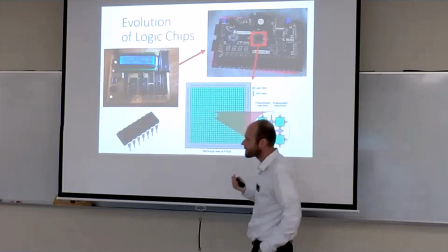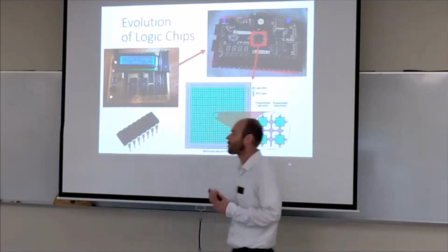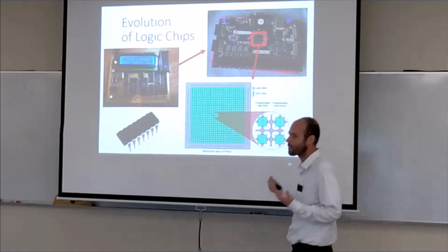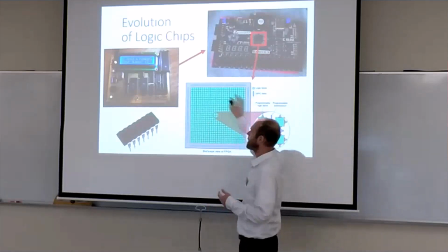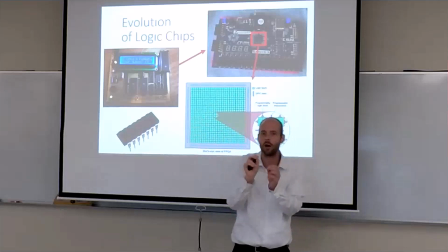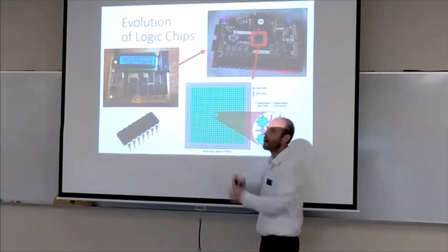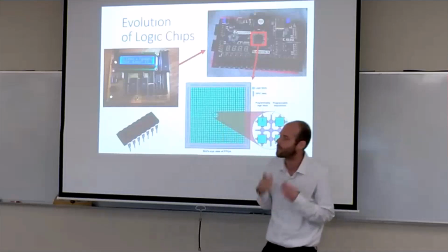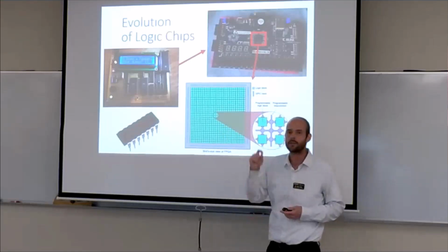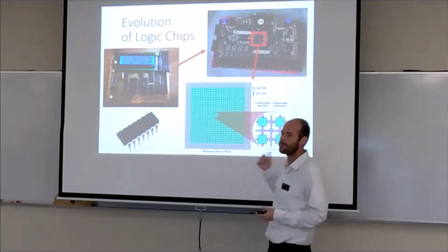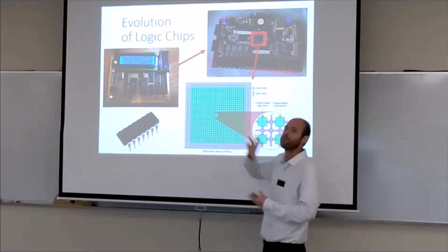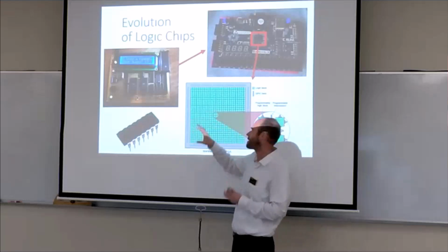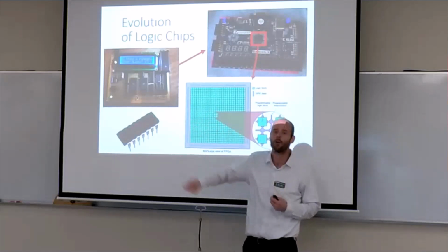However, the technology has moved forward, and in more recent decades, we have FPGAs, or field programmable gate arrays. Essentially, these are big meshes that can be burned or not burned at all the junctions. And by burning or not burning these junctions, connecting or not connecting them in a certain way, you can get the transistor effect out of these FPGAs, and they can be reprogrammed. So you can burn in an AND gate, an OR gate, a piece of logic, add 2 bits together. Then you could reprogram it if you wanted to.